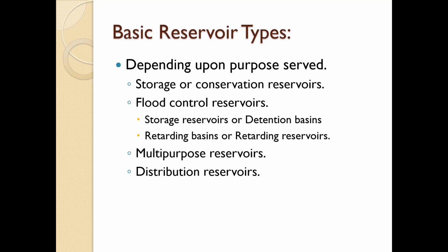The advantages of a retarding basin over gate-controlled detention basins are: one, the cost of gate installation is saved; and second, there are no gates, hence the possibility of human error and negligence in the operation is eliminated.